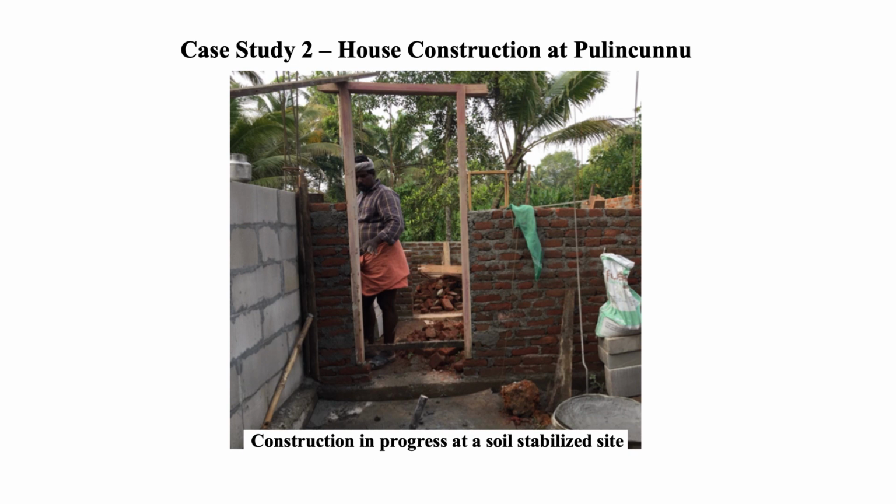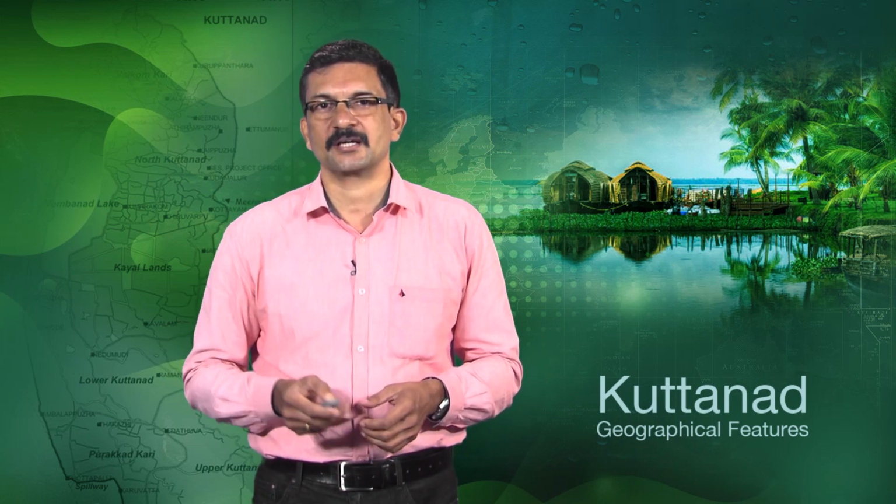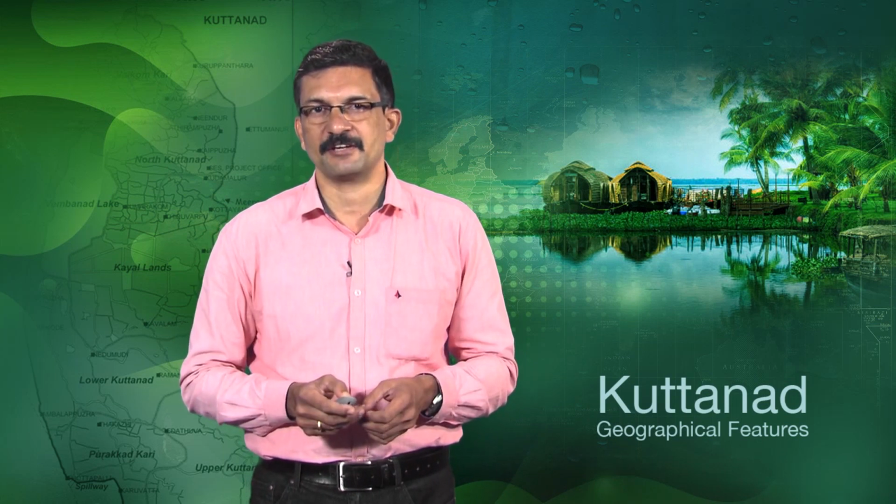Wherever there is a possibility of foundation settlement, wherever there is a large settlement of foundation, in those walls the superstructure in that portion was constructed with AAC blocks, which were lighter in weight. And wherever there is possibility of less settlement, we have used clay bricks also. So a kind of load adjustment was made in that fashion.